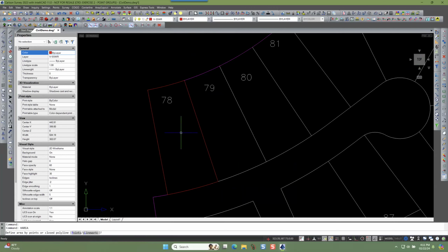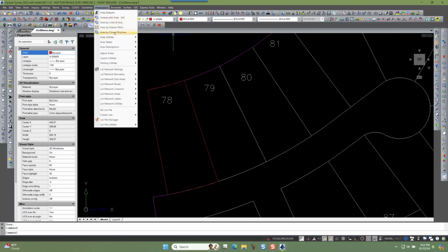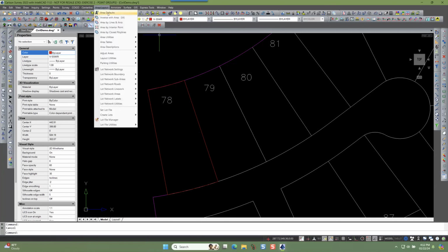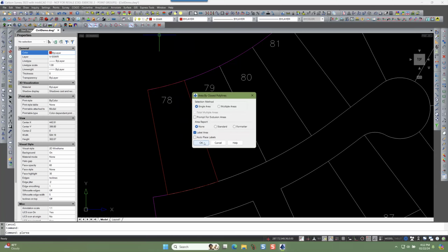That's the finished area by line work. Choose the red line. There's my hinge point. No remainder yards, acres. Enter the target area, 12,950. Now, if I close the polyline, good. I do by interior point.